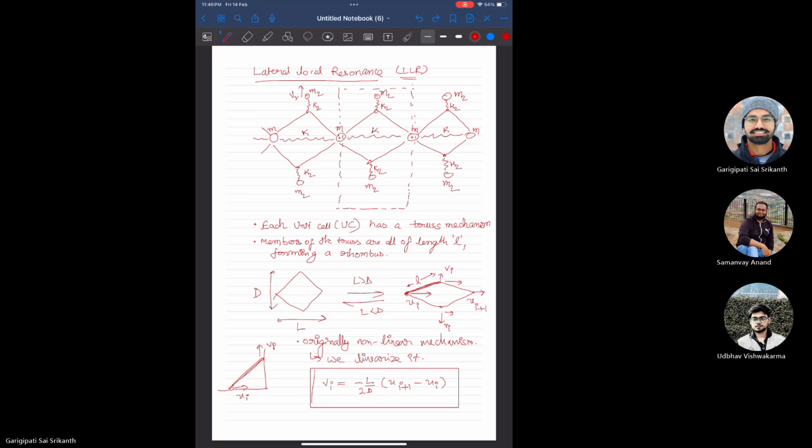So when most of the truss is moving here, let's say in the horizontal direction, we say that the stiffnesses are constrained in Y. But in reality, the way these equations have been considered in this paper, if M2 is constrained to Y-axis, but let's say this point moves, then the spring K2 will elongate.